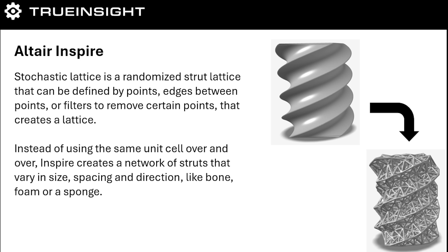Hey everyone. In this video, I plan to dive a little deeper into the stochastic lattice creation tools in Altair Inspire. Now, as opposed to a traditional lattice that uses a repeated pattern to create the network of struts, a stochastic lattice is a randomized strut lattice, and that can be defined by points or edges to create the network. These can be really useful for absorbing shock or sound waves, and are really common in medical and aerospace applications because of their ability to reduce the weight and maintain stiffness.